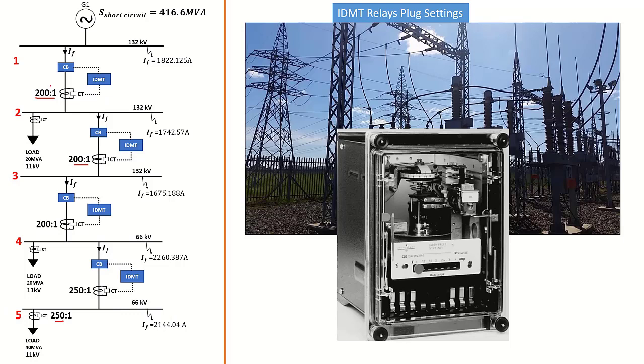Okay. So what is the story here? The story here is you have an IDMT relay, right? That is right here. And the IDMT relay needs to send a signal to the circuit breaker, and the circuit breaker must trip. But the IDMT relay itself needs to receive a signal based on what the current transformer is seeing from the current that is flowing this way.